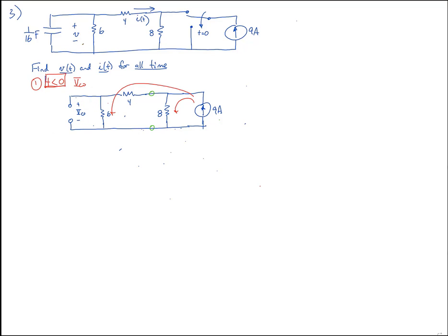And if you don't write it down, if you say, well, there's no current, so I don't need to write it down, the next thing you do is you'll transform it away. And now you'll end up finding some random voltage at some random part of the circuit, and you'll be wrong. So it's really important to keep that voltage in there so you know you can't transform away what you want to find. So your only option, since none of these resistors are in series or parallel, at least that won't destroy the thing you're trying to find, you've got to do that source transform.